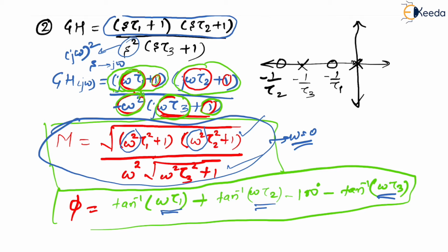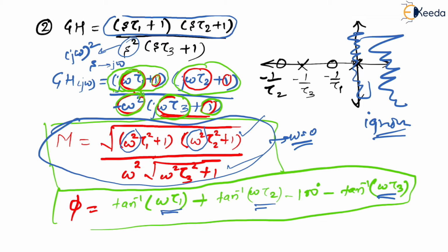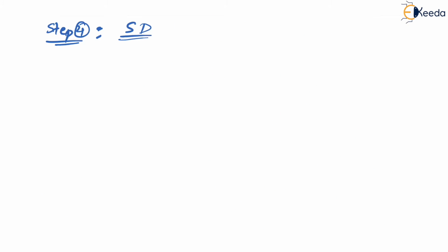So this is the pole-zero plot, right? Whatever is on the imaginary axis and on the right half, we are going to ignore, because we are not interested in it. Now the first thing: the zero is closer to the origin, which means the starting direction is anti-clockwise. Simple as that, we will now try to plot it.